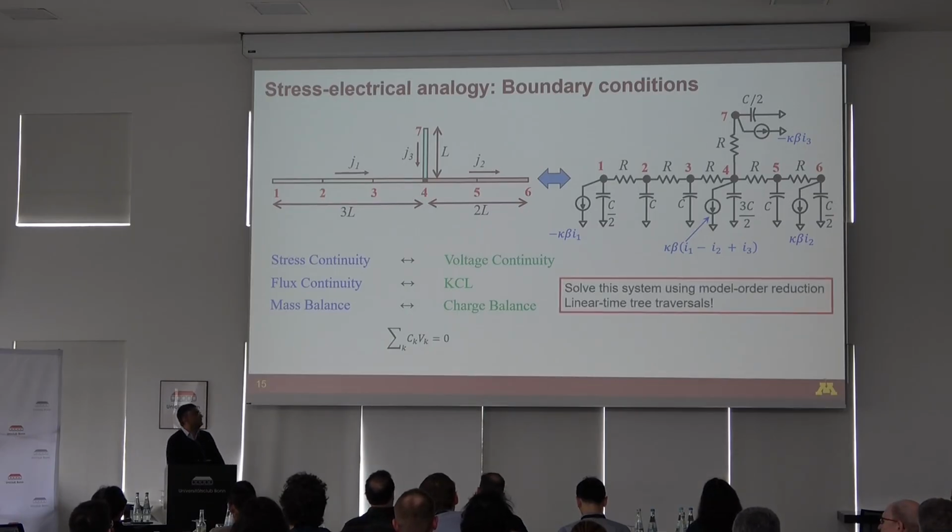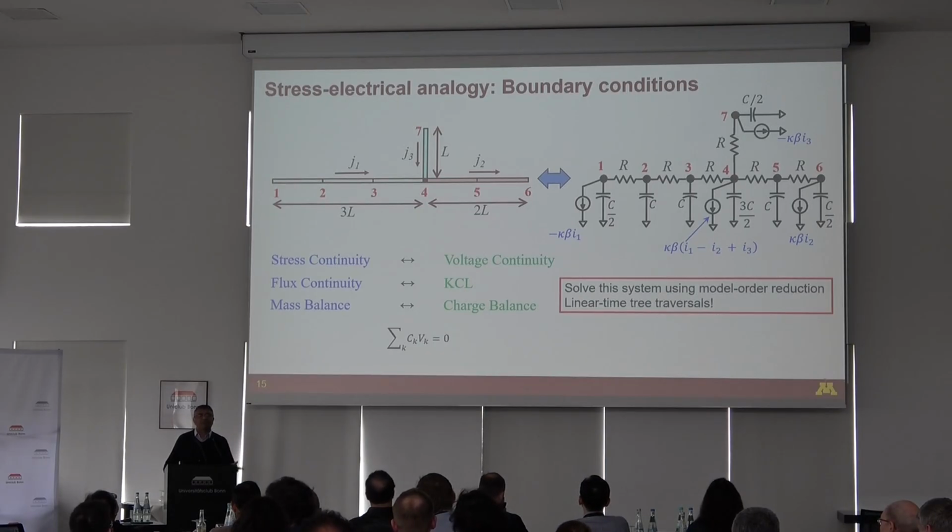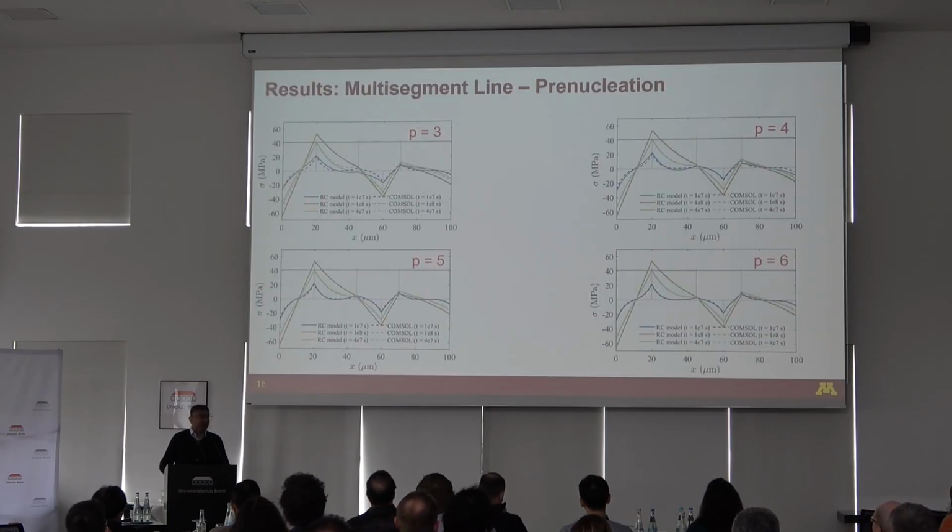In fact, we can even use model order reduction. And we know that we can solve RC circuits with these excitations in linear time, right? So this is the beauty of it, that if you just spend some time looking at it, you can translate it into a world that is more familiar, and you can use the insights that you are familiar with to leverage this. And basically, with all of this, steady state analysis and transient analysis can now be done in linear time for physics-based equations.